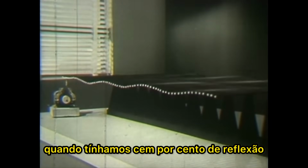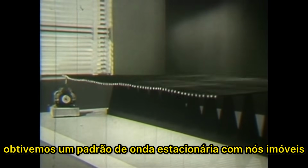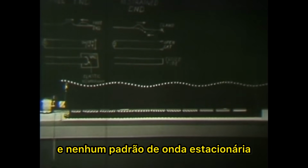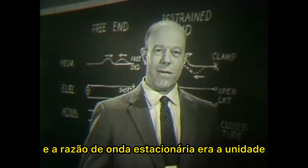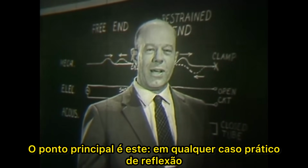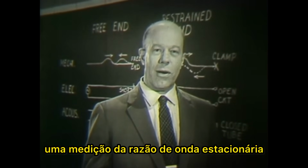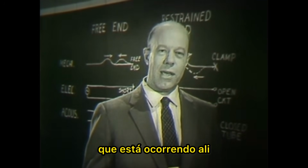Now recall that when we had 100% reflection, when the end of the machine was clamped, we obtained a standing wave pattern with motionless nodes. The standing wave ratio in that case was infinity. On the other hand, when I had a perfect impedance match, there was no reflection at all and no standing wave pattern. In that case, A max and A min were the same, and the standing wave ratio was unity. Now I think you can begin to see where I'm leading you. The punchline is this. In any practical case of reflection, a measurement of the standing wave ratio on the medium just ahead of the termination enables one to calculate the percent reflection that is taking place there.